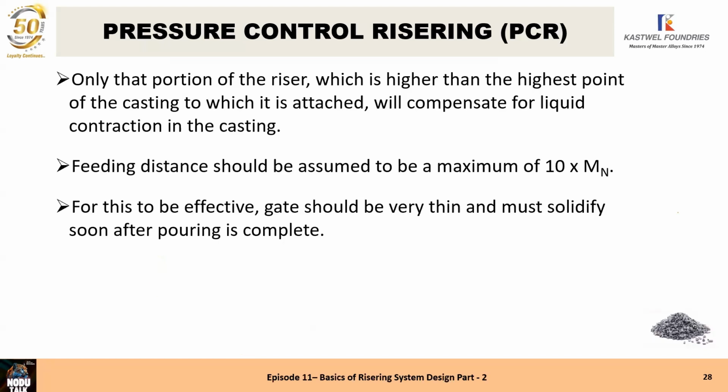We have seen now that only that portion of the riser which is higher than the highest point of the casting to which it is attached will compensate for the liquid contraction in the cast. I've explained to you in detail. This is very easy to understand now.